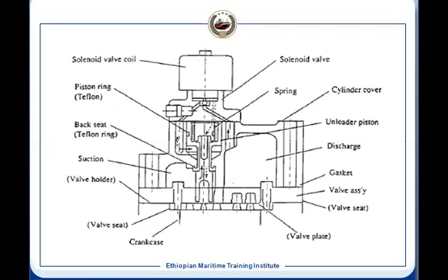Suction valve plate will remain open. Then the compressor piston is reciprocating, but during the compression the refrigerant will come out through the suction valve, so there will not be any compression. That's the way we unload it.